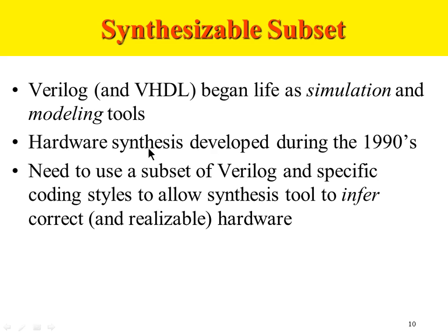So that was the key part that was developed in the 1990s. But the thing to remember is we have to use a subset of Verilog and certain coding styles or design styles to allow the synthesis tool to infer correct hardware. What this means is, for the synthesis software, the Verilog file is an input file. It will read the Verilog file, and based on your Verilog description, the synthesis tool will implement or infer. Infer means based on your Verilog, it will generate certain gate netlists and certain designs for you.